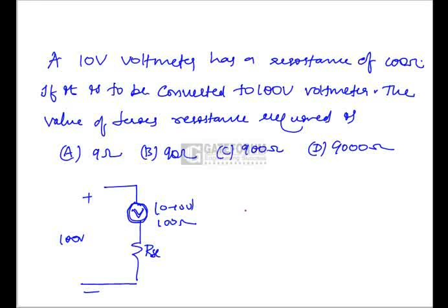Now Vm by Rm should be equal to Vsc by Rsc. So Rsc is equal to Vsc times Rm by Vm.